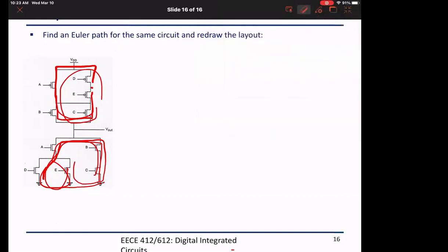I have a quick question here. If I adopt this diffusion, what is the capacitance at the output? What would the capacitance at the output be if it were one continuous diffusion, not disjoint or broken? In the P loop, how many times am I visiting the output node?